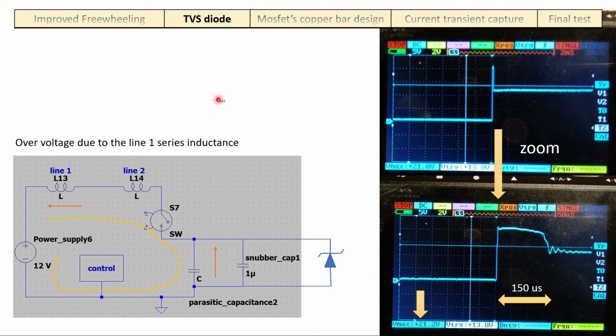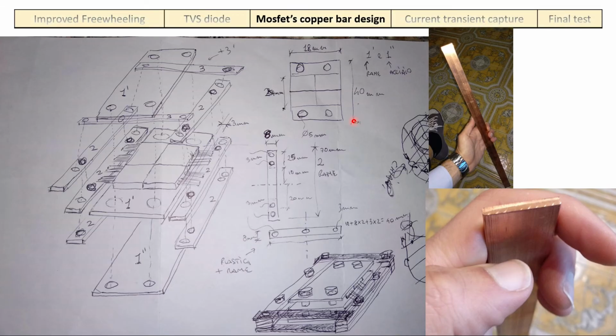So when I attached it to the strips, the current continued to flow through the strips, and I remember I risked damaging my batteries. So take care of it, put in more capacitance and as many TVS as available, because otherwise the MOSFET can fail.